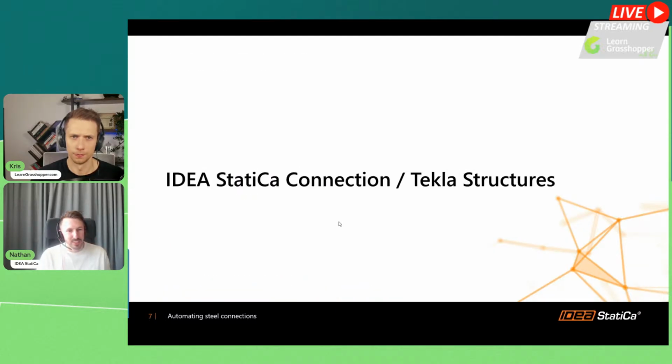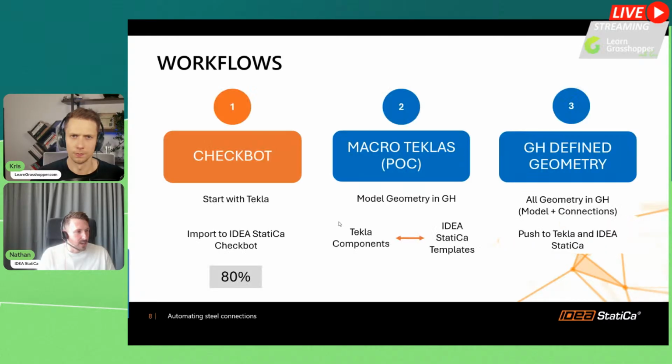So let's get into it. Idea Statica connection, which I'll mainly be talking about, and some of the possibilities with Tekla Structures. I'm going to present three workflows. The first one being, I guess, our standard workflow. This workflow is typically when you're starting modeling in Tekla, and you want to take that Tekla model and use Idea Statica for connection design.